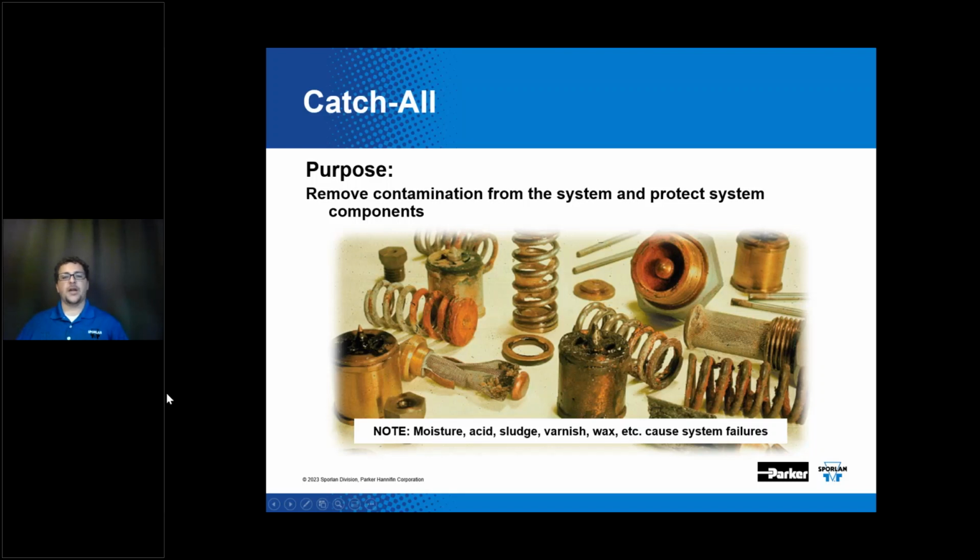All right, final thing is the contamination. I mentioned that system contamination can have very negative implications on system performance. We offer the Catch-All, which is intended to remove contamination from the system and protect the system components. What we say at Sporlan is that anything besides refrigerant and lubricant in the system is considered a contaminant.